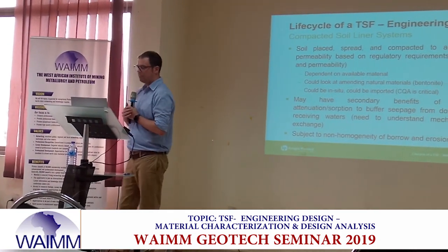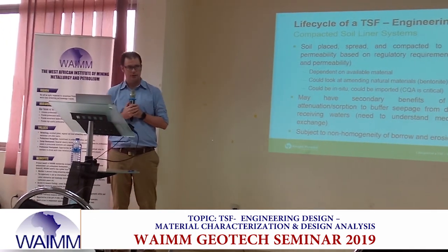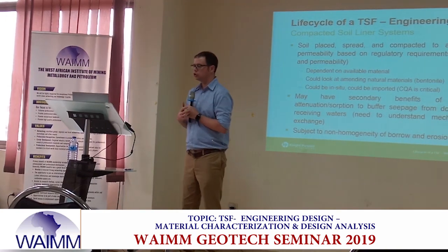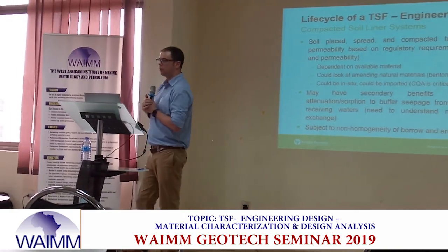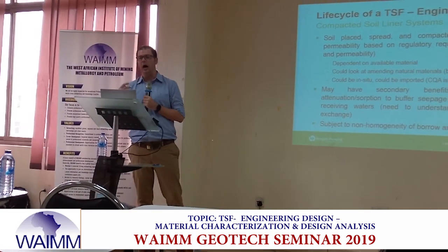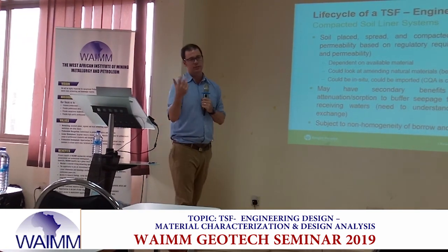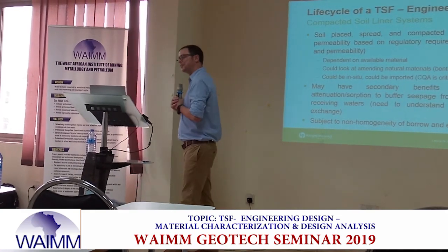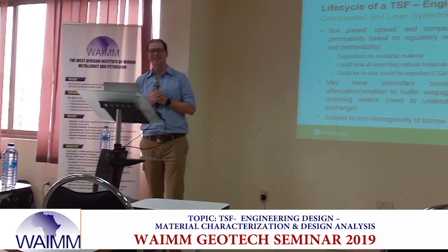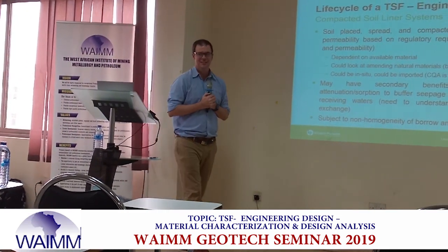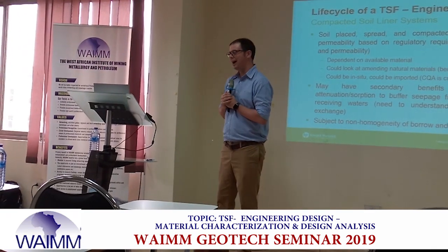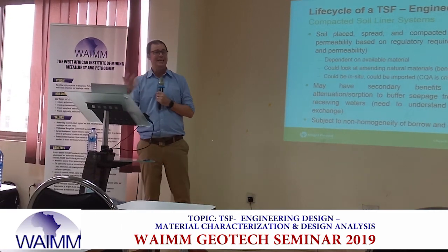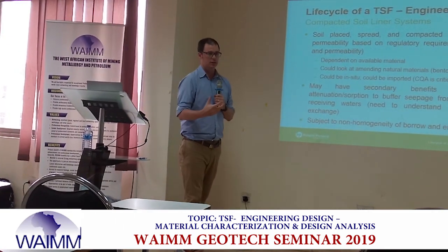There are some secondary benefits for compacted soil liners. Soil has a propensity to sorb different chemical constituents. It may actually lock up some of the chemical constituents that might leach out of a tailings mix. I'm not a geochemist. I know just enough geochemistry to get myself into a lot of trouble. Okay. So I will leave my comments on that secondary benefit to, it is known that it exists.